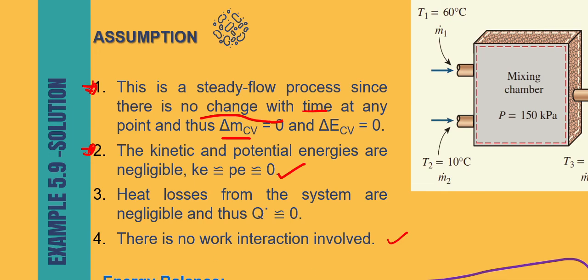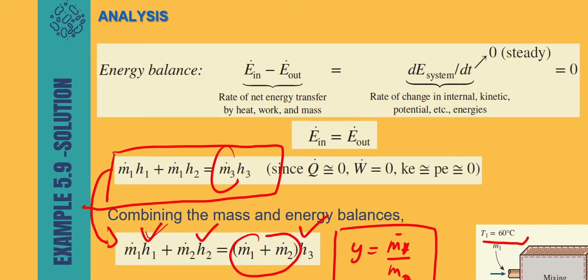You are only given a steam table, and then please understand well the change in state, from saturated, and then mixture, and then superheated. So you know, if at this temperature which is greater than saturation temperature, what is the state of the fluid? With this knowledge you can get the correct properties, whether enthalpy, internal energy, and whatnot. If you don't know the change in state, then you cannot find the correct value for your H.